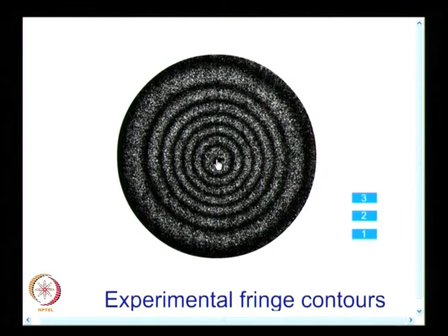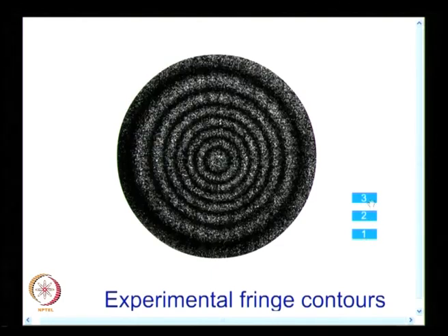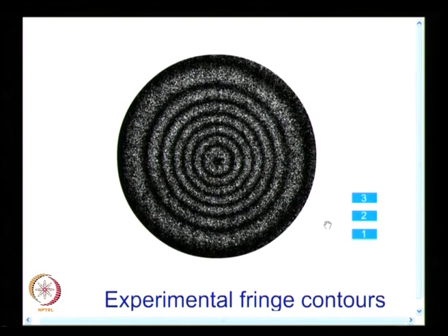What is the advantage here? You are able to get out of plane displacement by a whole field technique, but the fringes do not have high contrast. If you look at any of these speckle interferometric methods, they spend a lot of time on filtering. On the other hand, photoelastic fringes have very high contrast, and you need to do less post processing than in the case of speckle interferometry. These are the fringes you have, and this is again a function of load. Also make a neat, reasonable sketch of this.